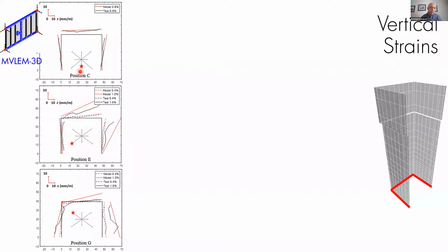As soon as I push this model in diagonal direction, the strain distributions in the test are becoming quite nonlinear, especially as we progress and have more and more displacement demand. And the model just simply, by definition, cannot capture that nonlinear strain distribution, and instead it does the straight line, right? That's all it can do. And this is the reason the neutral axis depth is not predicted correctly. You have much more tension strains, therefore you have much more tension capacity, and that's why we're overestimating the capacity in those diagonal directions. Similarly for the other diagonal direction over here.